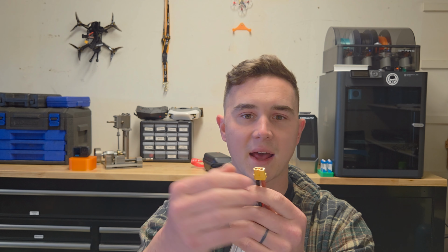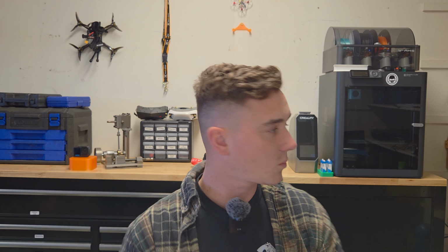So you have a main lead, you have a battery lead, which is this. This specific adapter is called an XT60. There's other ones that exist that are XT30 or XT90 that have to do with the size. Most commonly on like 5 and 7 inch, you're going to see an XT60. Then you have what's called the balance lead. So the balance lead goes from the lead to all the individual cells. And what it does is when you plug it into a charger, like this one, or the one you see over there, it allows the charger to charge individual cells instead of the battery as a whole. You can get into a cell mismatch, which can damage your battery and really cause some problems for you, but this helps to get ahead of it.